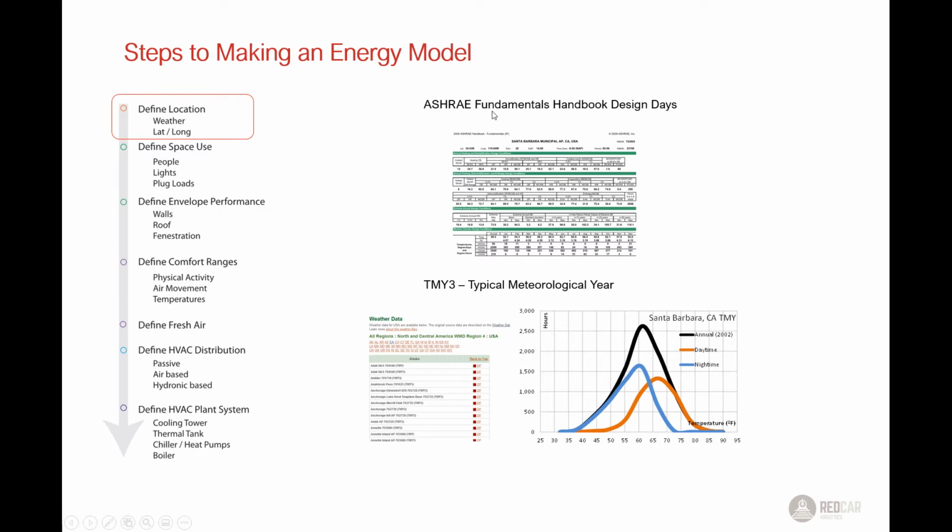We also need a design day. A design day represents either the hottest or coldest conditions that location experiences. And these design days are used to help understand how big the heating system or the air conditioning system should be. And if I was to estimate that size, if I didn't put it in myself, I need to reference a design day condition, such that I know I can heat my building in Santa Barbara here to 34.7 degrees outside. I can still meet 70 degrees inside.